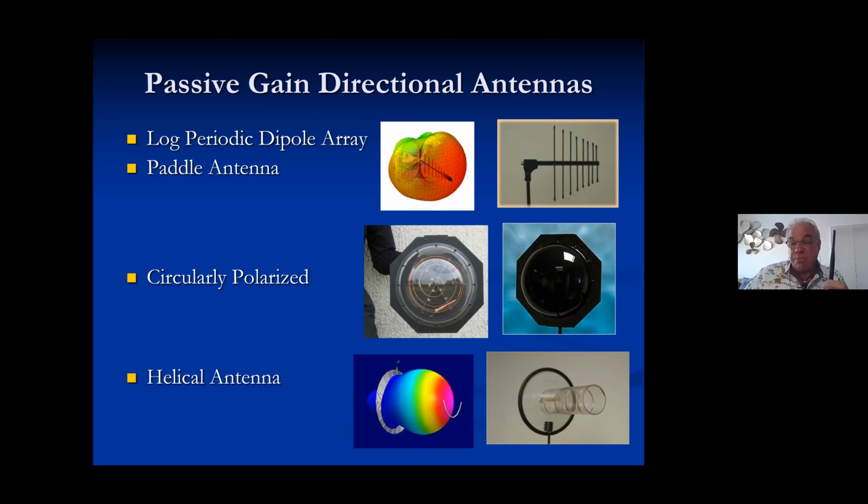Let's get a sweaty body dancing, with conduction against the sweat and the body, and throw the worst possible antenna on this device you could have, right? That's what an in-ear receiver is. So you need to do as much as you can on the transmit side to get that 100% transfer. So I always recommend a CP or helical antenna for transmitters.